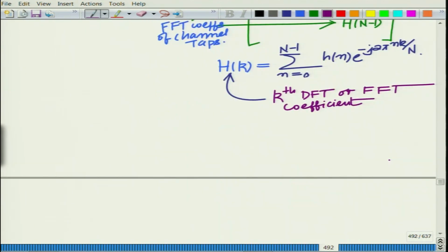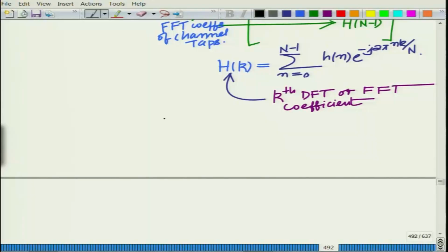Okay. Now, remember in OFDM the estimation process ends with single tap equalization, because there you are pre-processing using the IFFT matrix, but here that is not the case. We still have to recover the symbols, the small x bar. Therefore, we now have to perform the IFFT, that is F IFFT times lambda inverse y bar.